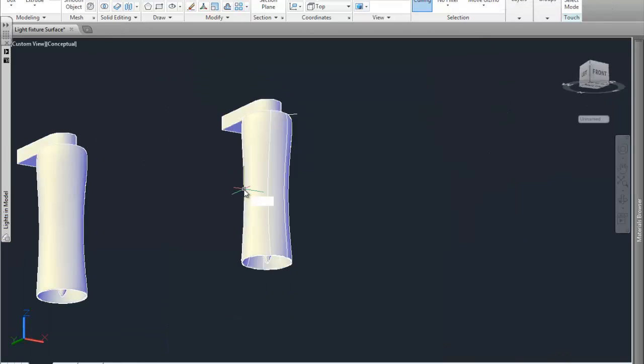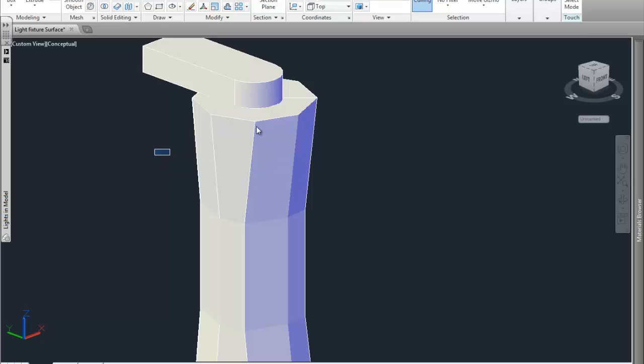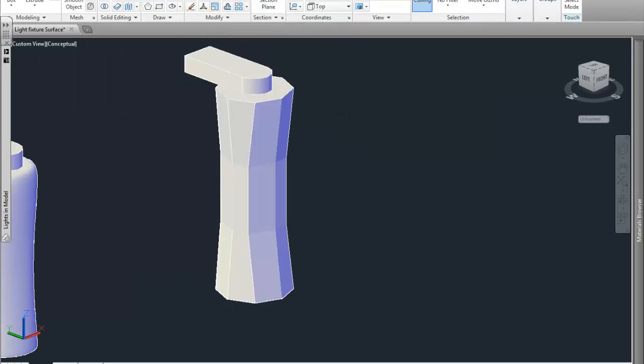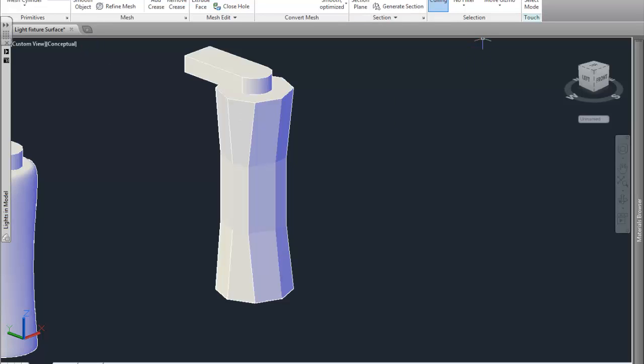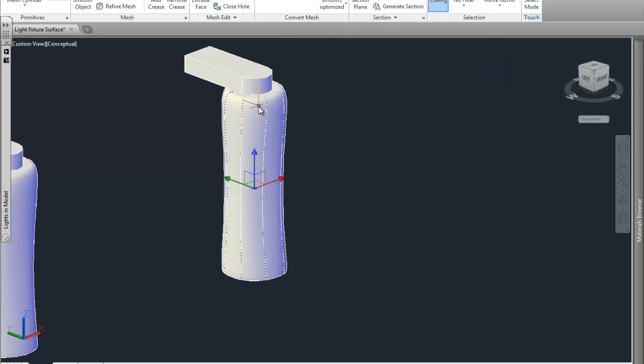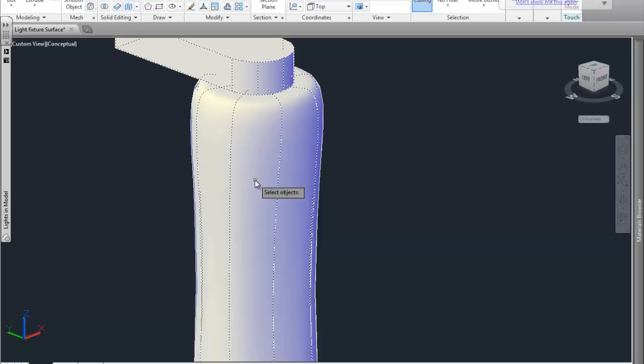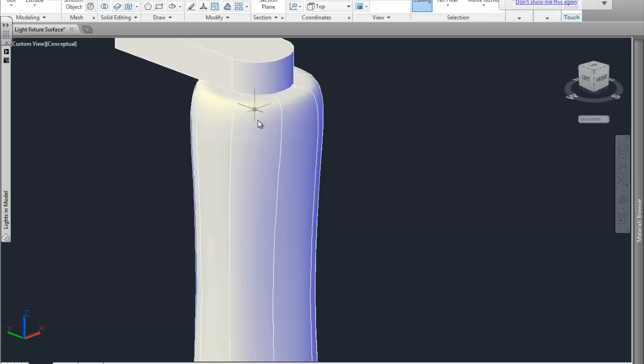And there is a different command to be used if I want to convert a mesh into a solid. It's a little trickier. So you go to mesh, convert to solid. I do that. So maybe now it should work. I go back to home. I union the two objects. Yeah, it's still not working.